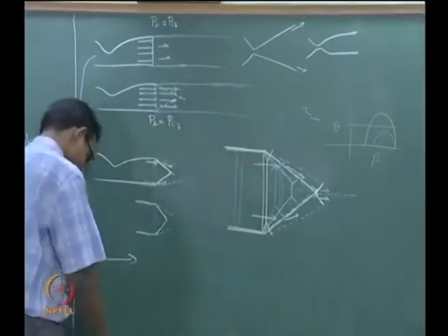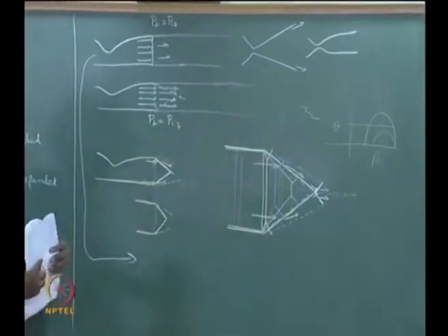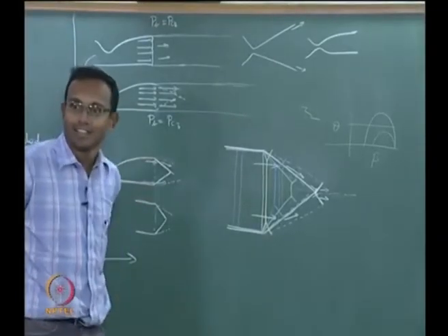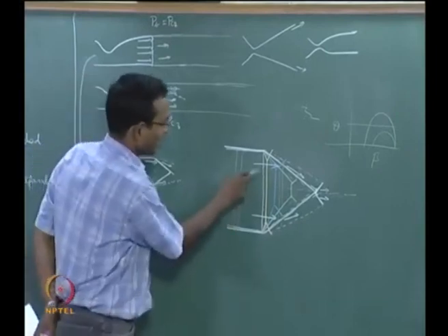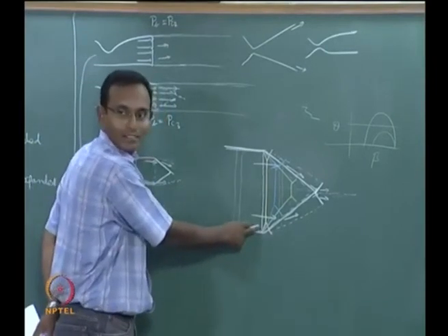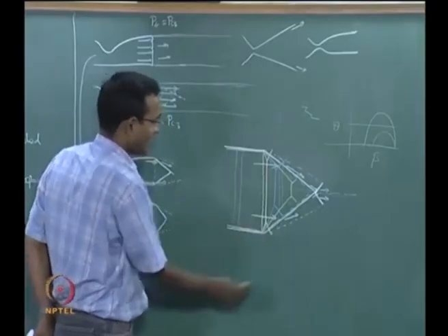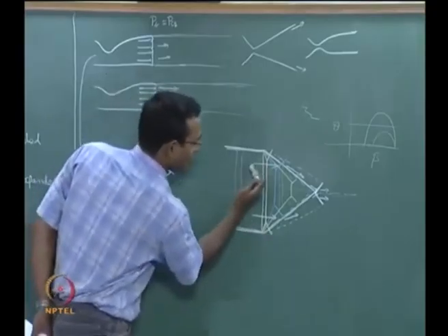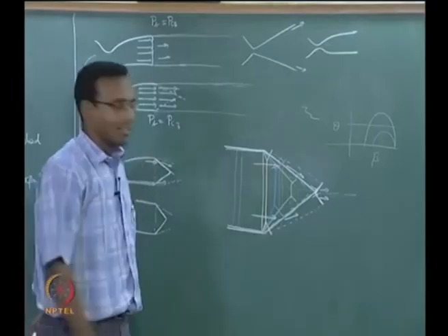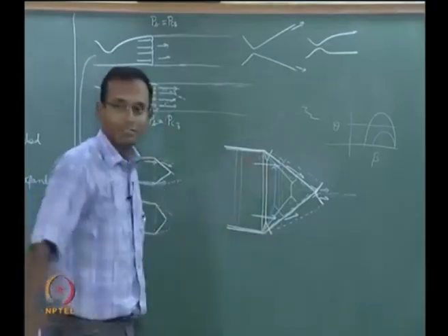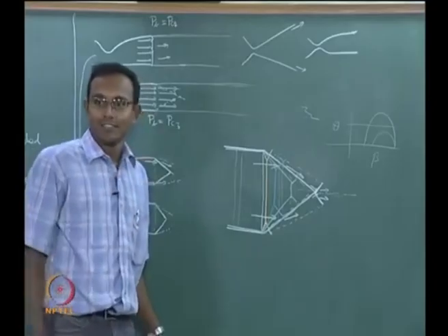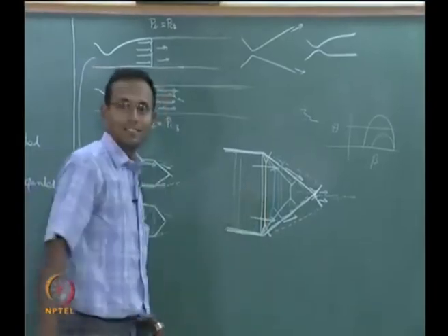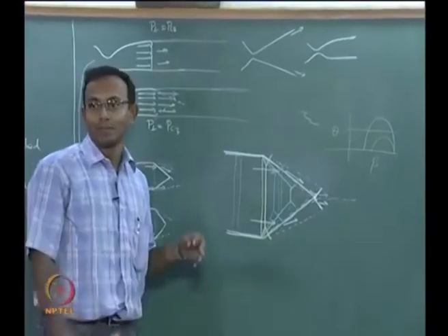So if you look at it, shock is doing a continuous change. If I think about PC2, my shock is sitting on the exit like this, white. If I decrease it slightly, it is almost normal shock most of the places, only some portions it is oblique shock, which means only those regions the pressure is lesser, other regions it is roughly the same as this original exit pressure.